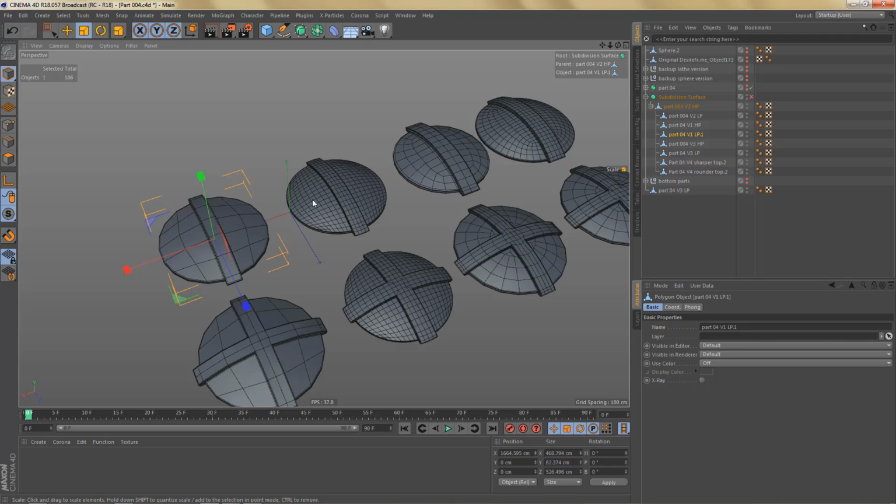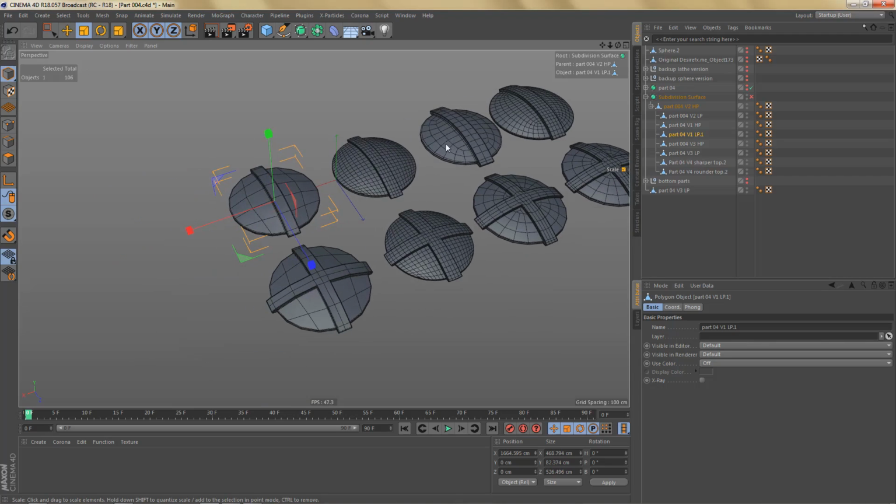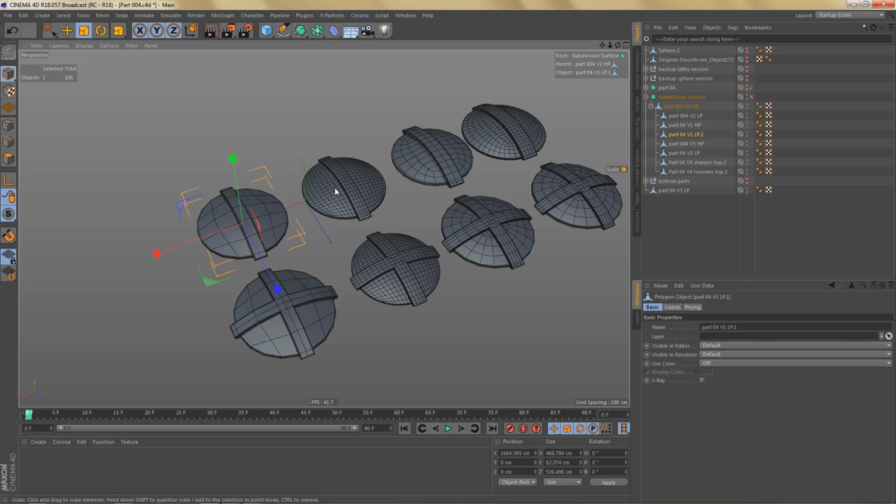version, a higher poly version that is intended to, you know, add smaller details maybe. And you can see I have different topology over here for the lower poly object, and I have a higher poly version as well. And the reason I'm showing you this is because when you do this kind of modeling, always try and do different versions, use different topology and see how things turn out. All of these are actually pretty decent, but I do prefer this type of topology, and that's the kind of topology that we just created for the lid.